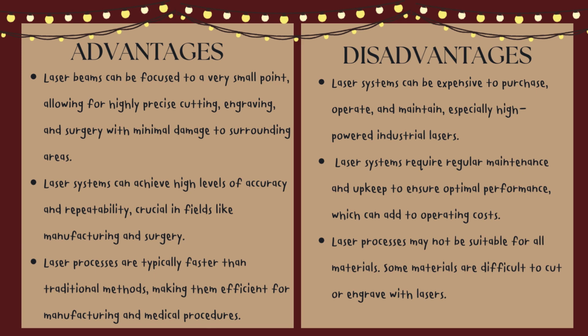And last but not least, it's about reflective surfaces. Certain materials with highly reflective surfaces can reflect the laser beam, making them challenging to work with and potentially hazardous. For example, laser welding of highly reflective material like copper can be challenging due to the beam deflection.